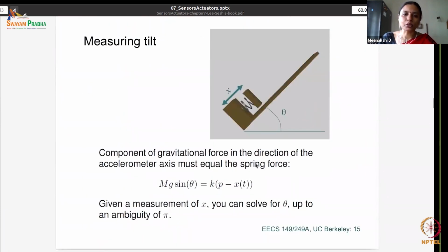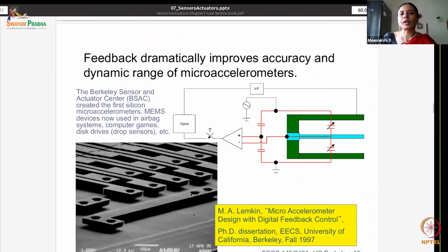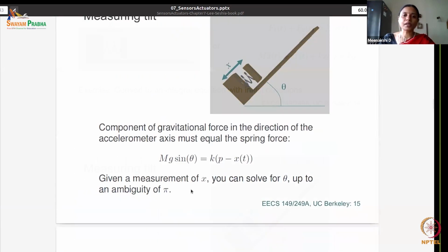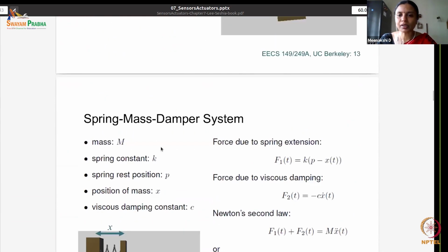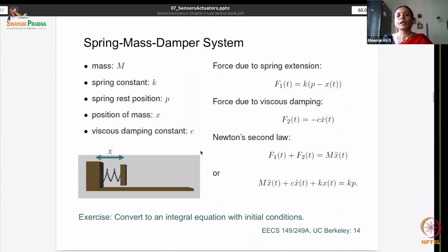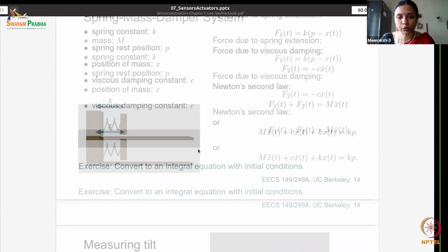You can use the same sensor to measure tilt, in which case the equation becomes what is given here. You can use other sensors, and you can use a micro-level accelerometer, in which case the equations change drastically, and so on. So for each kind of sensor, we understand the high-level physics or the dynamics of it, consider the equations, and try to model or fit the curves of these equations using appropriate lookup tables, by which the physical phenomenon gets discretized. And that discrete entity is what we consider for our software implementation, or for our algorithm to process.